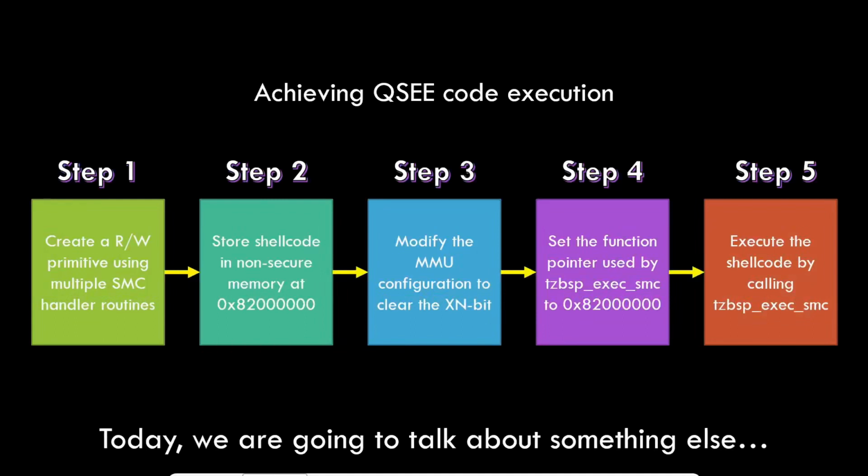We don't care, we just store it conveniently in RE memory, because then we can just modify the MMU configuration to enable that range, map that, it's actually already mapped, map the RE range into the TE MMU and clear the XN bit. At this point, we use one of the functions in order to trigger execution from this address, and then we are basically executing our arbitrary code.